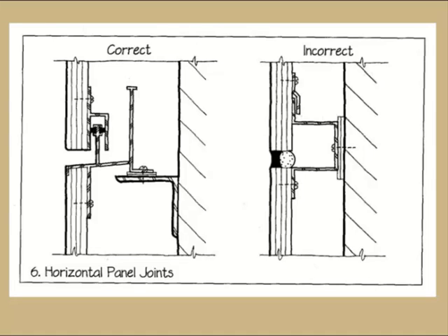The left vertical leg shows a gasketed connection into the upper panel, and any moisture that comes through the panel, whether it's through a crack or whatever up above, comes down, and that right vertical leg acts as a stop for that, so it can't get to the building, and it isolates it and maintains that barrier.